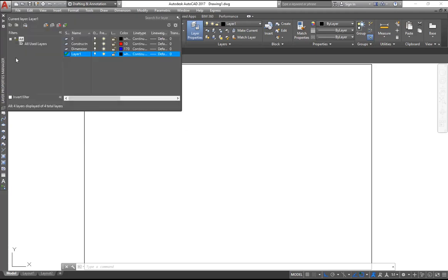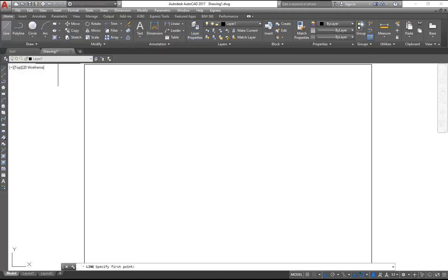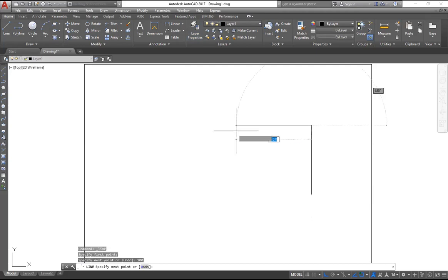Quickly, let me close this. I pick on segmented lines. You can use segmented line to do that. You start from a place where you can easily get a good point. Now I can move up. Now I type 100 from the keyboard, press enter, so that is 100. Now I type 200 here from the keyboard, that is 200.